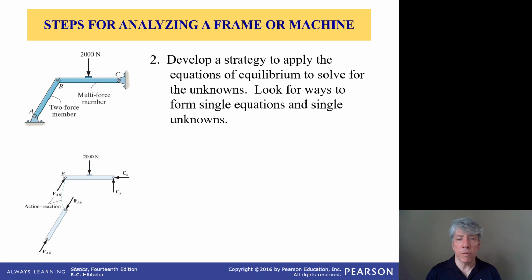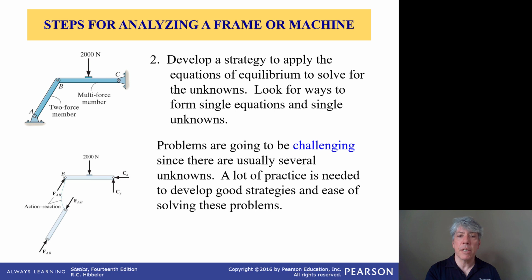After that, make sure you develop a strategy for applying the equations of equilibrium to the various free body diagrams in order to solve for the unknown forces. You always want to find a way to use a single equation to solve for a single unknown if possible, because that simplifies the algebra. It's not always possible, and you'll see examples of this in my other videos, but if possible, certainly you want to simplify your algebraic work and come up with some type of plan for how you're going to go through the frame or the machine, member by member, and solve for the unknown forces as needed.